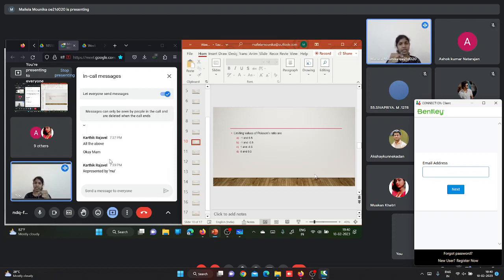The loading is axial tensile load. It is represented by nu, and it is the ratio between lateral strain to the longitudinal strain. What is meant? If I apply load onto this material, it will get elongated in the longitudinal direction.